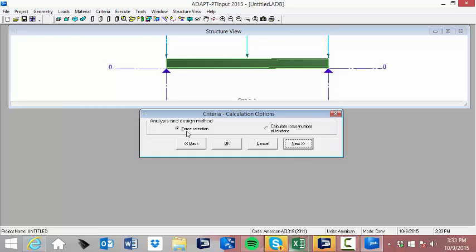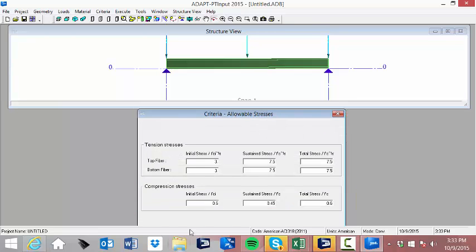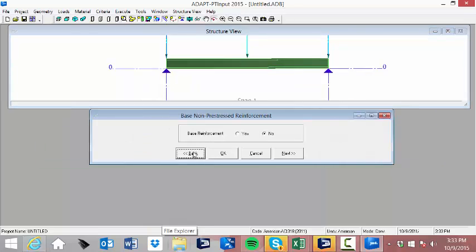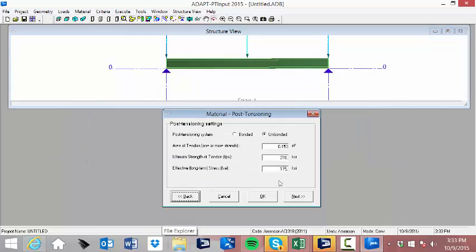A lot of times for I-beams, these are actually pre-stressed girders, and you would want to reduce or eliminate the active nature of the friction loss and the seating loss in some cases. So to do that, we would either have to go back and adjust our value for the effective stress input, which is shown here. This is assuming we do have friction loss and seating loss plus the long-term loss.